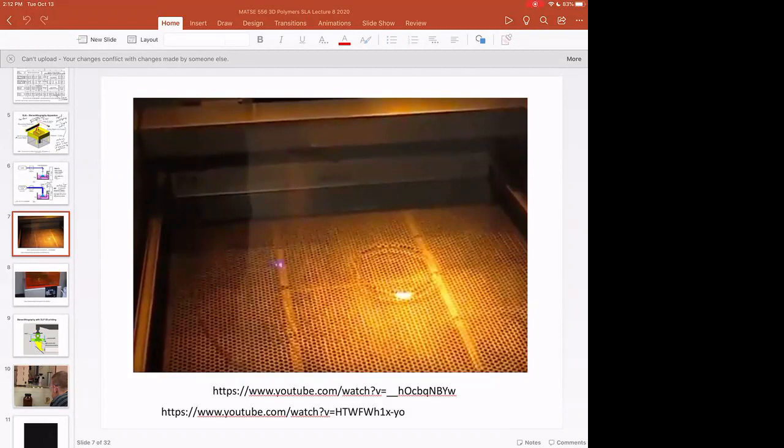If you look at the contact angle of toluene, which is an organic liquid, it's always a lot lower than the contact angle for water, because water is a high surface tension liquid because of its unique structure. But polymers tend to be good at wetting, and the viscosity is tuned for the specific process and also for the speed of the process, because viscosity is resistance to flow.